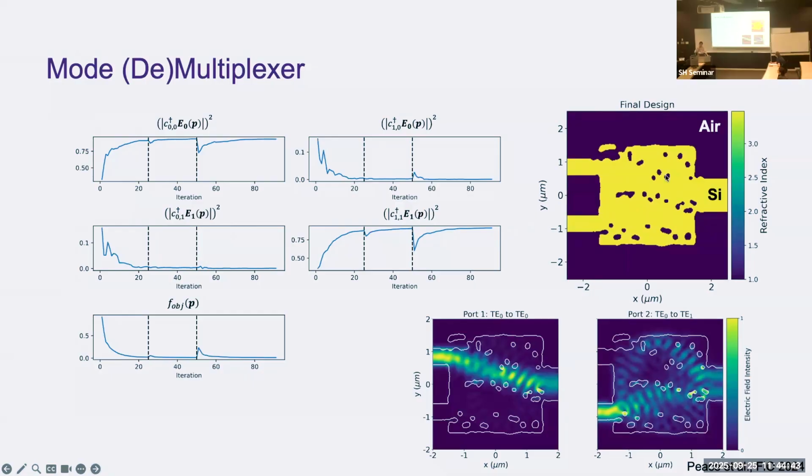When you're talking about silicon, there is only one correct index of refraction for a particular wavelength, but the computer doesn't know that. So we just let the permittivity be continuous, assigning anything that will make this device work. Those are the continuous stages of the optimization. These are the cost functions: I'm trying to optimize transmission and minimize crosstalk.